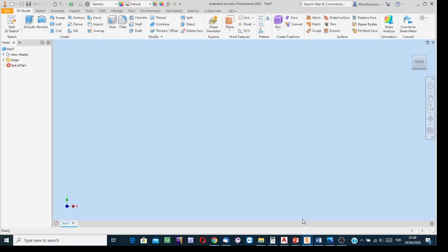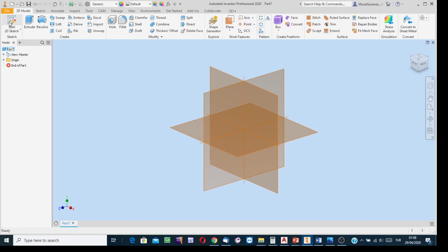And then yes, the buffer will be in the 3D mode, the 3D environment in Inventor. Modeling starts from the sketching stage, so click on the Start Sketch button. If the process to apply subsequently is extrusion, revolve, sweep, or loft, the sketch to use is to be two-dimensional. So click on the two-dimensional sketch option. And then this is the following stage.